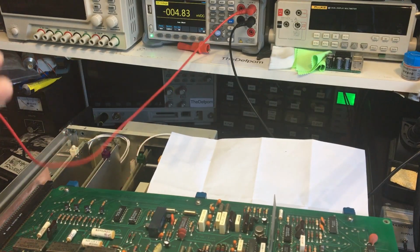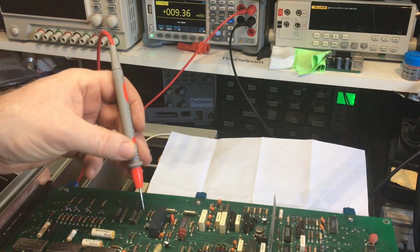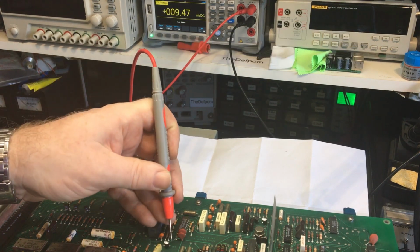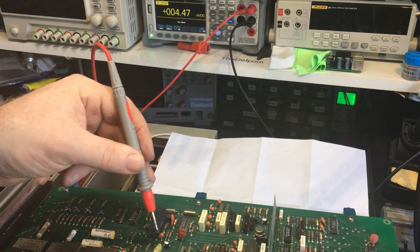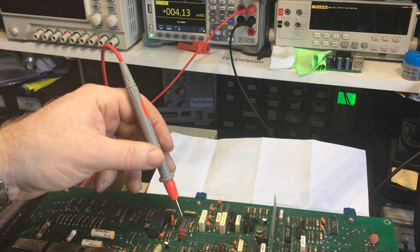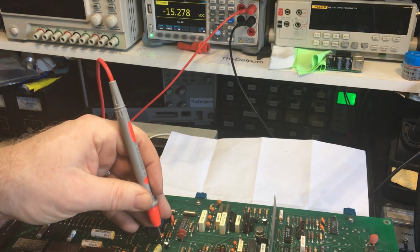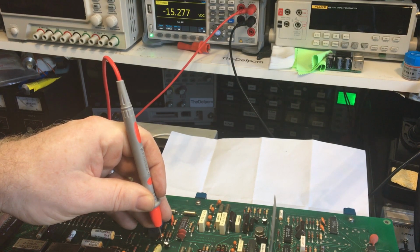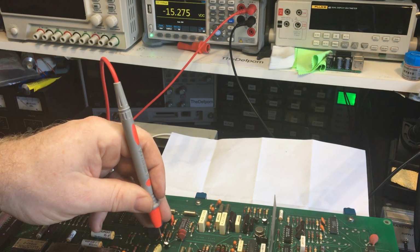Okay, so now I'm trying to figure out whether the K5 relay is operating correctly. I've measured those transistors to make sure they're switching. That's fine. This Q32 right here is the FET, which should be switching as well, and that shunts across the output of this IC here. So the FET here is that pin. Yep. So when it's on, it goes to minus 15 volts. When it's off, it goes to nothing. It's just floating, right? So the FET is switching.